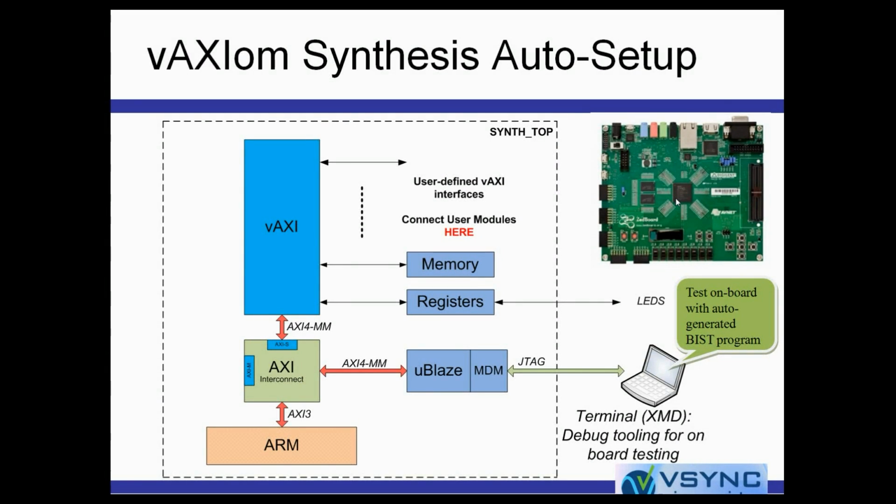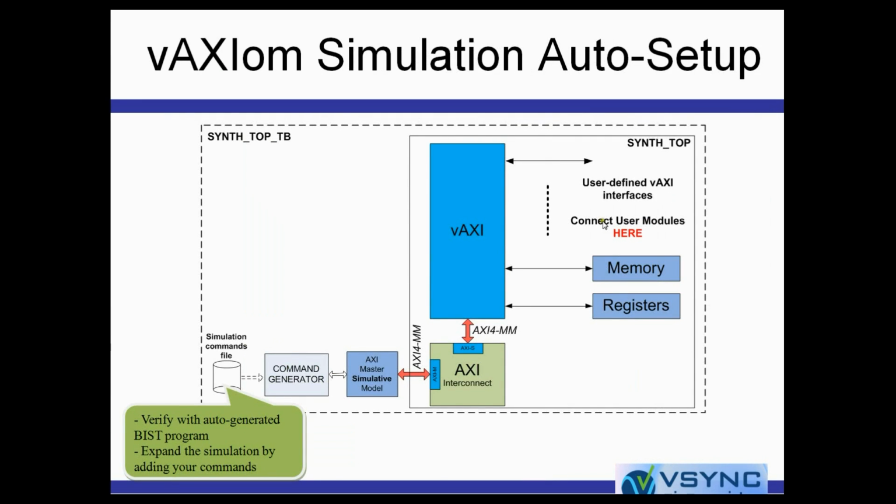In addition, the vAXIom platform will generate around the synthesizable top additional test bench environment, where the ARM processor will be replaced by a special master module which will execute commands written in a simple commands file, and the commands will be translated to AXI transactions towards the memory address space of the user.